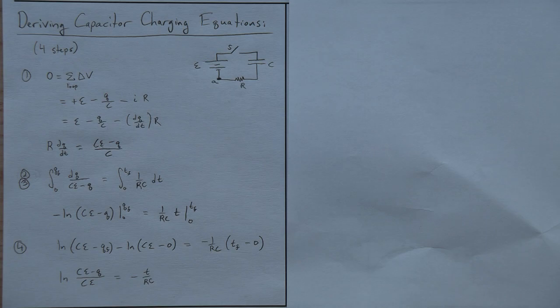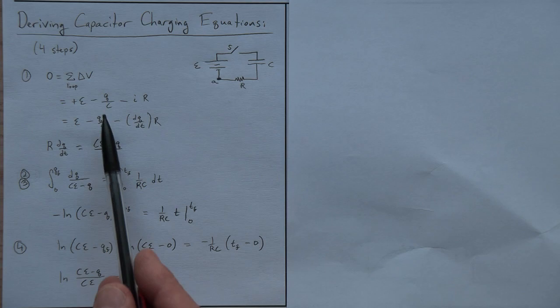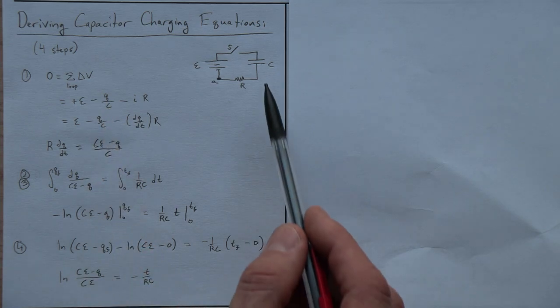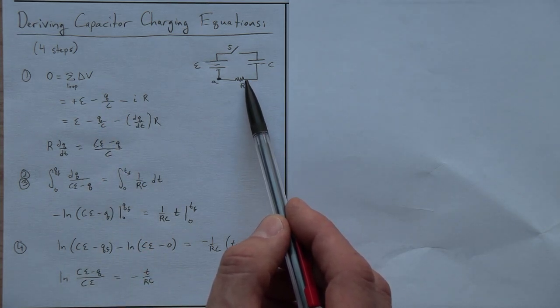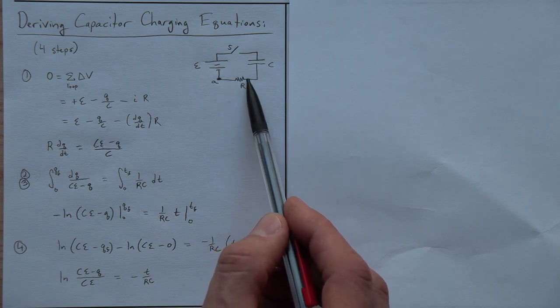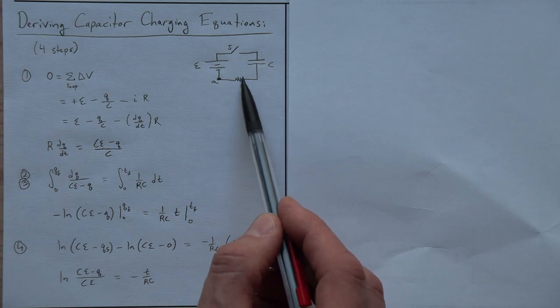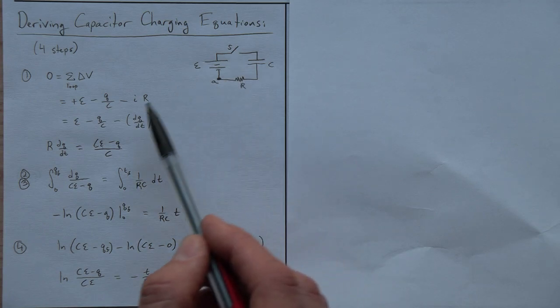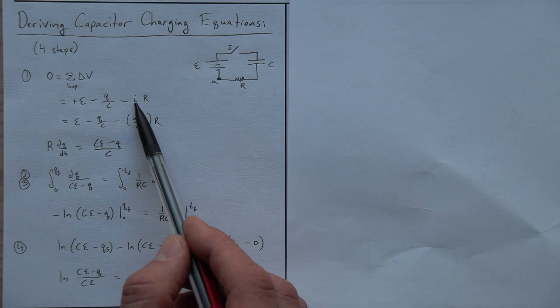Again, that comes from C equals Q over V, solving for V, the basic capacitor equation. The ant keeps walking, encounters the resistor R, and walks downstream through the resistor, downhill, right? If you're going with a river down a mountain, you're going downhill, so you go down in voltage, minus IR.